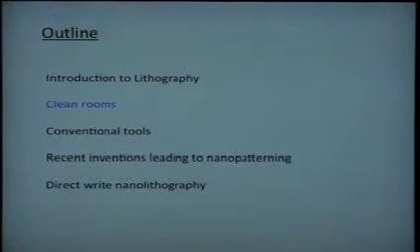But before you practice any kind of lithography, you have to worry about the environment around you. Okay? If I start patterning in this particular hall, if I'm trying to do, for example, a 10 nanometer pattern of a molecular ink or something, and as I go on writing, I will have a lot of dust particles coming over and decorating the substrate, right? It's like, you have in this room dust particles which are measuring 10 micron, 1 micron, 0.5 micron, even 100 nanometer. All are big features compared to the pattern I'm writing.